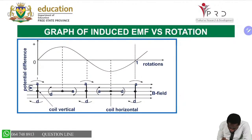Now, if you check at time zero, at this time, the coil, this is the magnetic field. So our magnetic field is from north to south based on that direction that you are seeing there. Now, if the coil is in that plane, lying perpendicular to the magnetic field, hence it's moving parallel to the magnetic field. There is the field, there is the movement of the coil. It's moving parallel to the field, so it's zero.